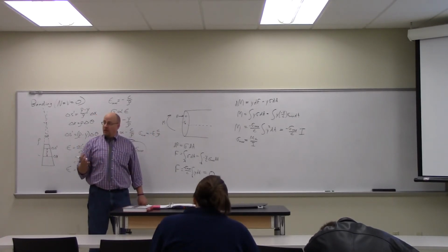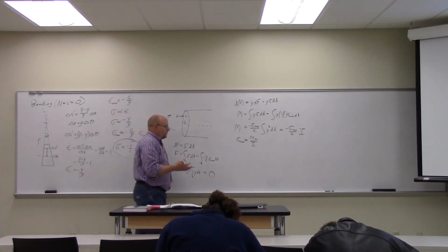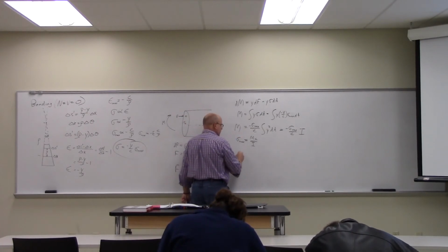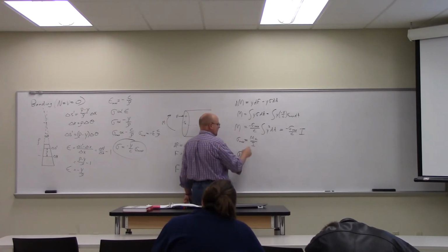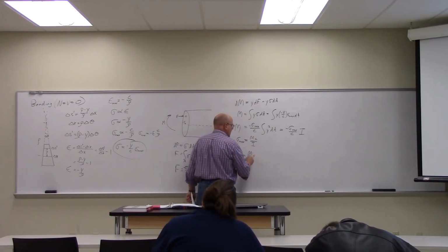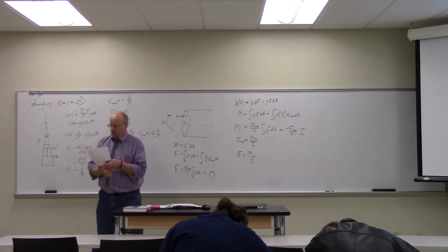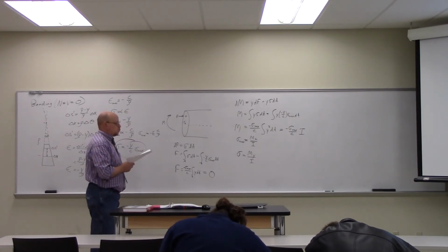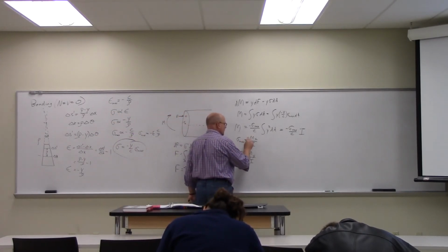Because this is what we're after. Again, we want to know the stress state in the bar. That's where we started. So we're trying to find the stress state. Well, the maximum stress is Mc over I, or the stress at any other point within this volume of material, or within that interface, is going to be My over I. Actually, I forgot I left out my minus signs.